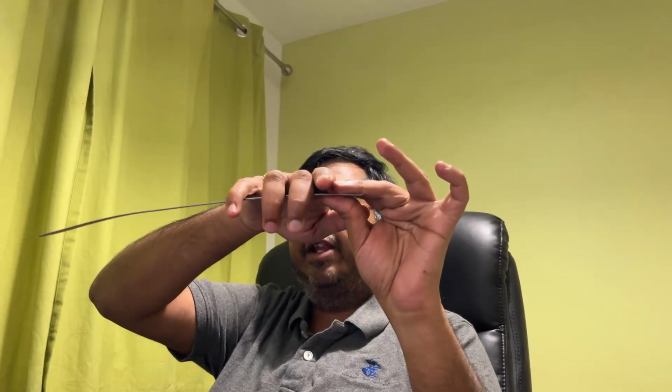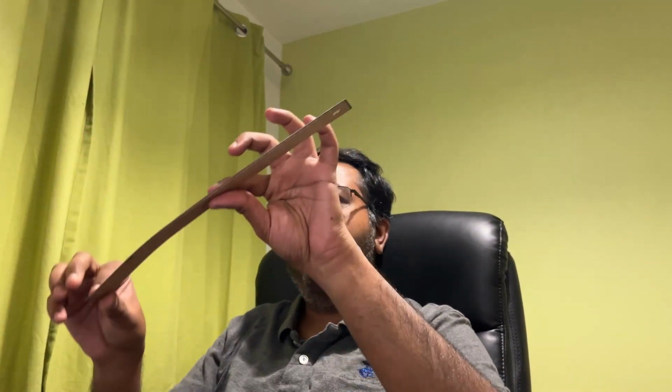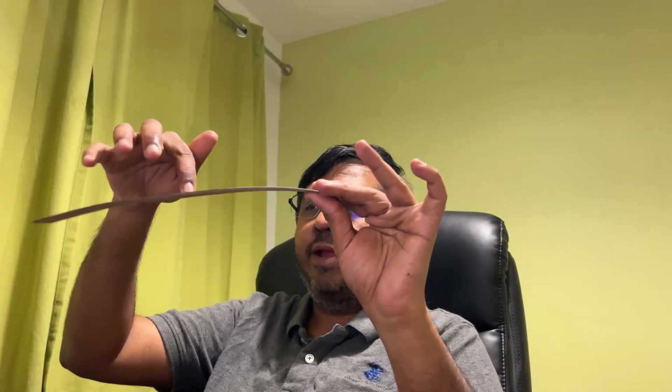If I look at this beam, if I'm going to apply a load here, everything on the right side of this load, which is this side, experiences some bending moment, but everything on this side is just undergoing a rigid body rotation. There's no real deflection or change in shape. It is just moving in a rigid body manner. So everything along here is just rotating about this point. Everything up to this point is deflecting because there's a bending moment, and everything here is just rotating in a rigid body manner.